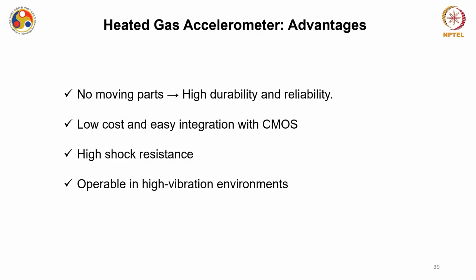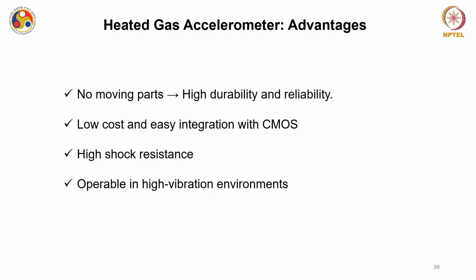Okay. And they have a number of advantages, like the biggest advantage is there is no moving part. So it's only the gas which is shifting its position from right to left depending on how the device is getting accelerated. Okay. And the fabrication is also not very complicated. They are low cost and easily integratable with CMOS technology. Okay. And since no cantilever or suspended mass kind of structure is there, they can have high shock resistance. Okay. And they can operate in high vibration environments. We have seen that it can withstand acceleration of the order of 50,000 G.